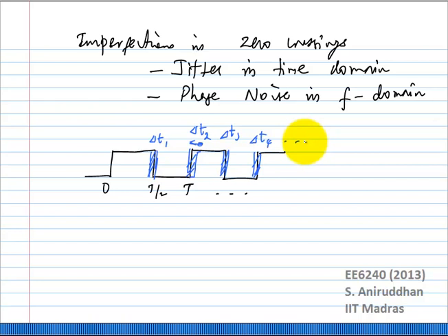Now you need to find a way to characterize this jitter, as we called it. How do you characterize this jitter? First of all, it's based on noise. So the only way of characterizing it is in statistical form, right? So you can talk about things like RMS jitter, right? There is period to period jitter and all kinds of ways to characterize this. Okay, but the important thing to understand is that you are doing a statistical characterization of this jitter.